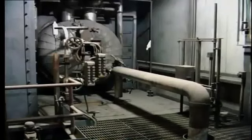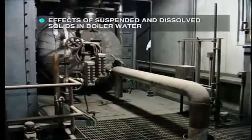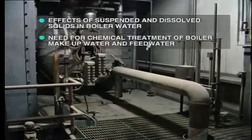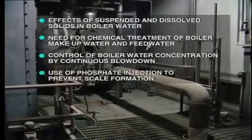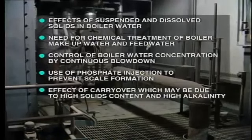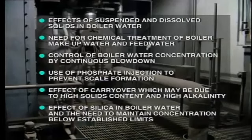So far in this brief review of boiler conditioning, we have looked at the effect of suspended and dissolved solids in boiler water, the need for chemical treatment of boiler makeup water and feed water, the control of boiler water concentration by continuous blowdown, the use of phosphate injection to prevent scale formation, the effect of carryover, which may be due to high solids content and high alkalinity, the effect of silica in boiler water, and the need to maintain concentration below established limits.